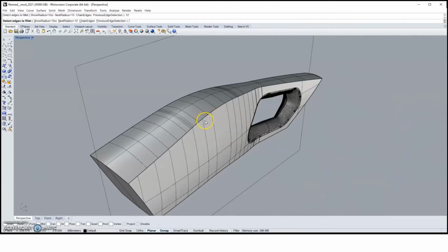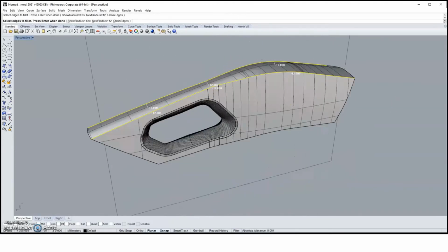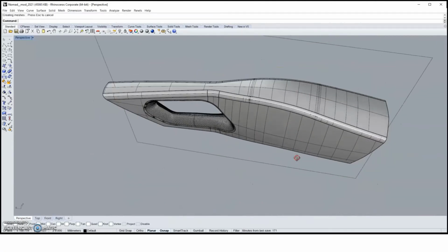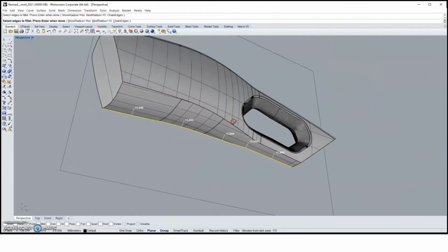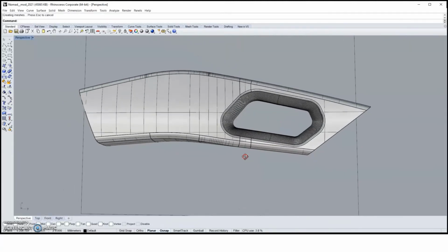So we decided that the radius could be too big, so we're going to make it a little bit smaller. Sometimes it's an evaluative process where we look at it, and then we modify it from here. And for the bottom curve, we're trying to select a bigger radius there, 15 mm radius. And then we're going to do an overall radius on the two edges as well.